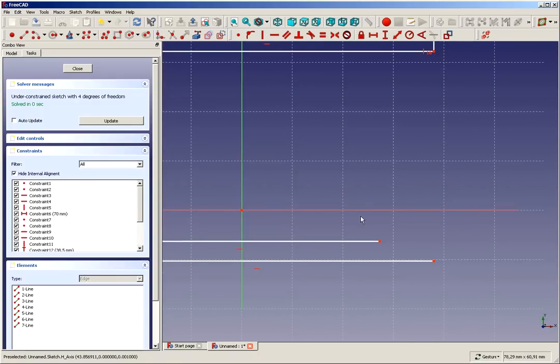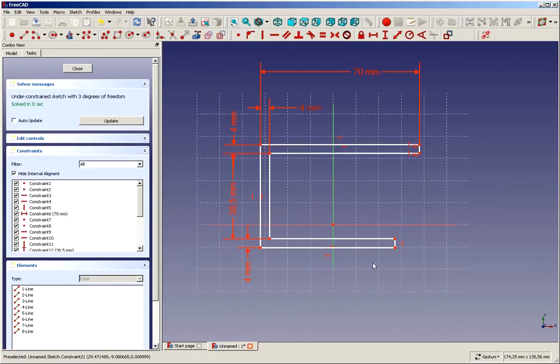So we're doing the same here. This time I'm doing it in a different way, which is to also put it somewhere. First, oh no, we're going to do it differently. We're going to switch to coincident constraining mode, which means now you can see the little red dot at the cursor, and for each subsequent 2 points that I'm clicking, it will automatically constrain them. We can do the same with this constraint, which is a vertical constraint on the selected items. Click them and voila, it is vertical.